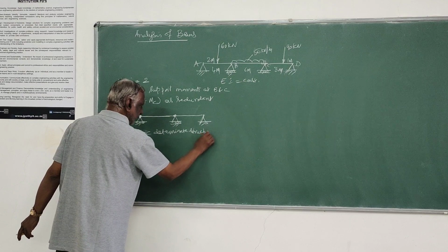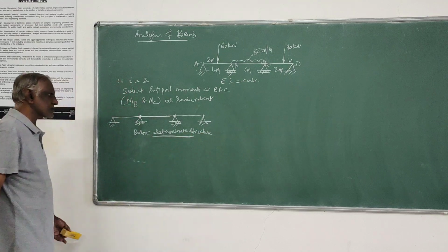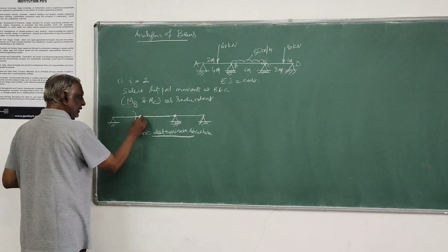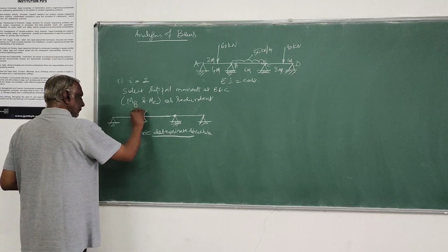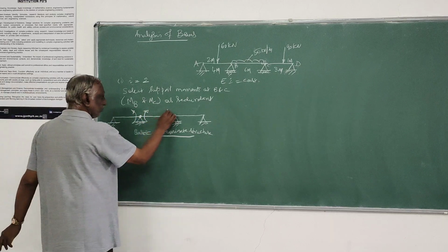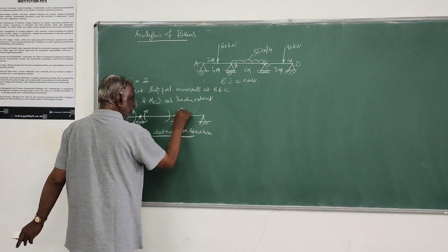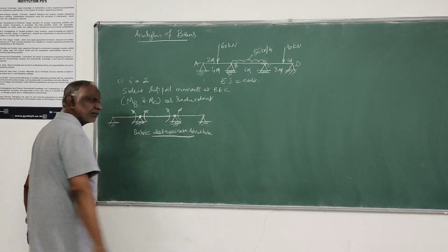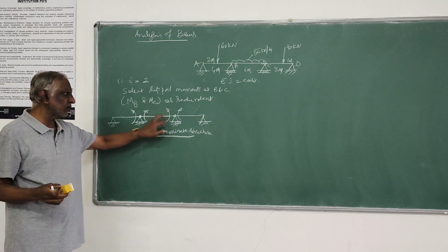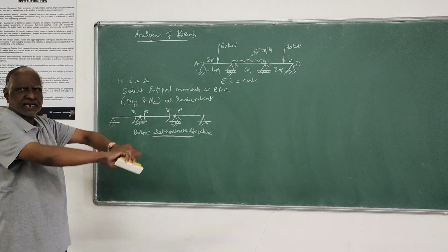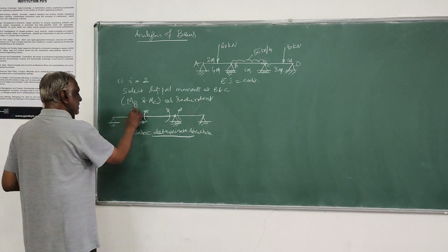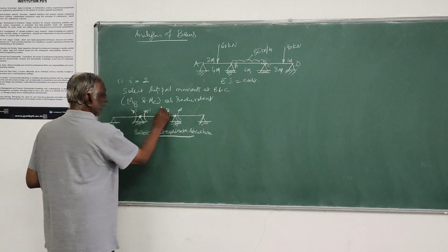And the direction of the redundant force, or the coordinates of the redundant force, in this particular case you can select by arrows in this fashion. Always the sagging type of moment is positive like this. So on left side you can take clockwise, on right side anti-clockwise. It is sagging type of moment in each span. This you take as the coordinate direction.